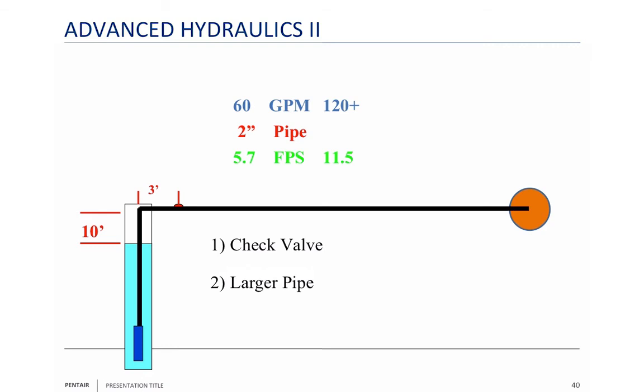Number 3 answer is, well, what is a sprinkler head? It's really nothing more than a flow restrictor. So what if instead of waiting to the end of the line to put a flow restrictor, we put a flow restrictor in right away? Okay. Now the problem is it's got to be under the water. And the reason it's got to be under the water is that when it turns on, it immediately goes to 60 gallons a minute. Otherwise, you're going to have that banging still taking place.